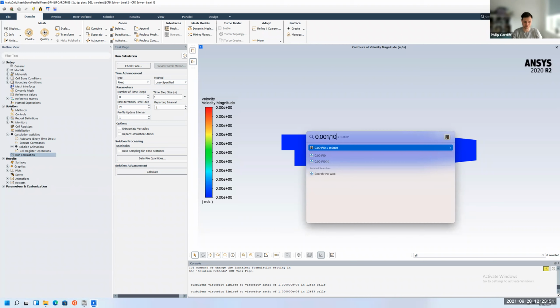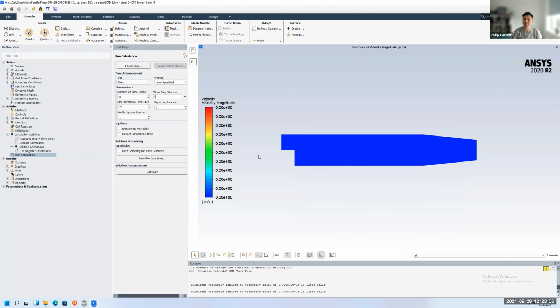The implementation in Fluent allows you to go a little bit bigger. But we can just try it out, and if it blows up and doesn't converge, we can just reduce it afterwards. So our time step, we're going to go 1e-4. How many time steps? I'm not going to run this until it reaches steady state.